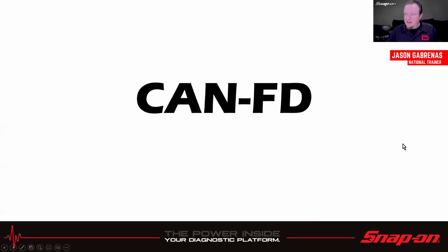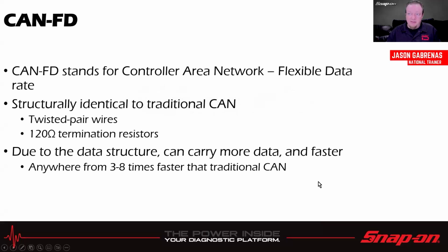Now let's talk about CANFD. CANFD is kind of the newer version of CAN that's out there. Some manufacturers use it. Many manufacturers use it internally on the vehicle. It doesn't terminate out to the DLC. Sometimes it does, but most of the time it doesn't.